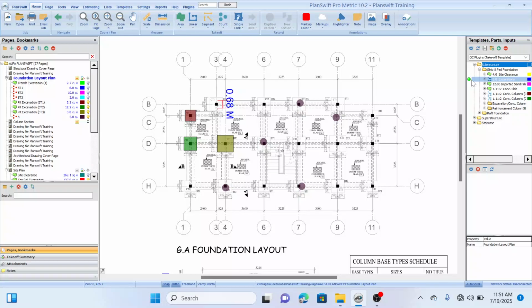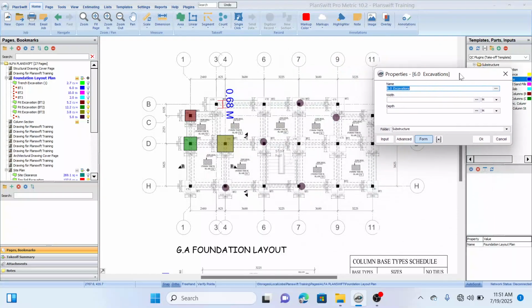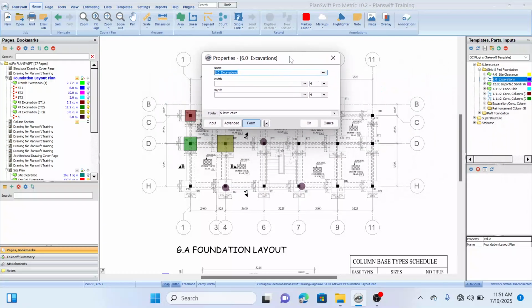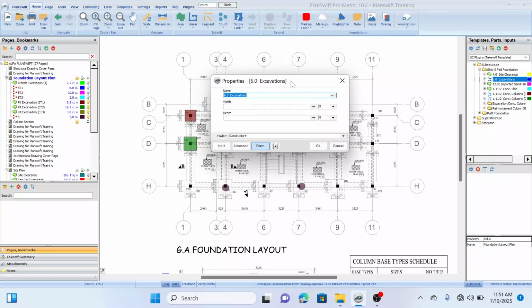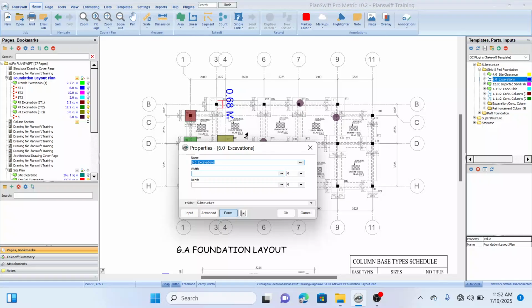To activate the plugin, you click on the green icon in front of that plugin, the way you click on the green button in front of your tools to activate them. Now the plugin is asking for two values: the width of our foundation and the depth. After inputting the width and the depth, we are going to trace the gaps on this plan.